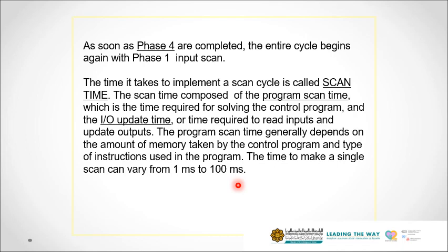So your input updating rate should be much slower than this cycle of operation. Otherwise, for very fast operation, PLC is not a good choice. For very fast change in input, PLC will not be a good choice. You need a high frequency data acquisition system in that case.